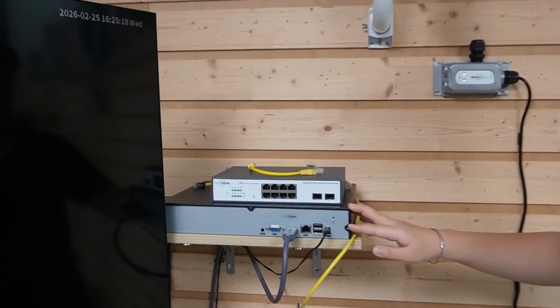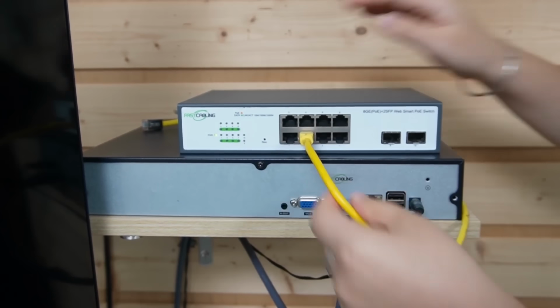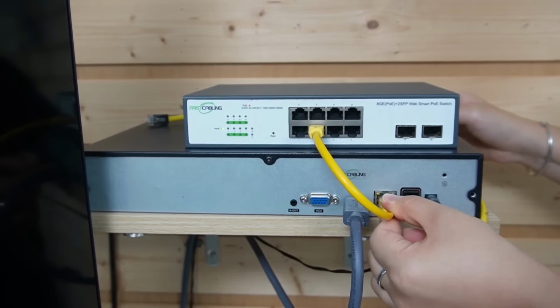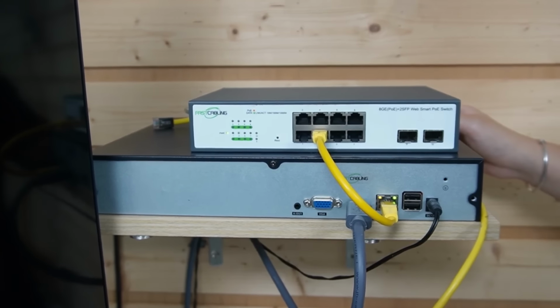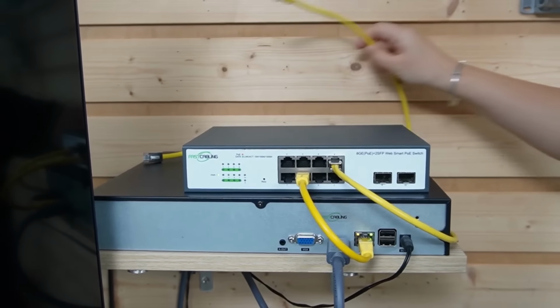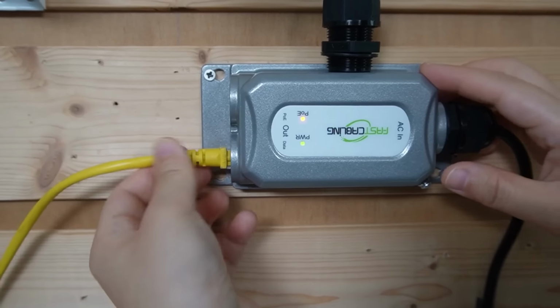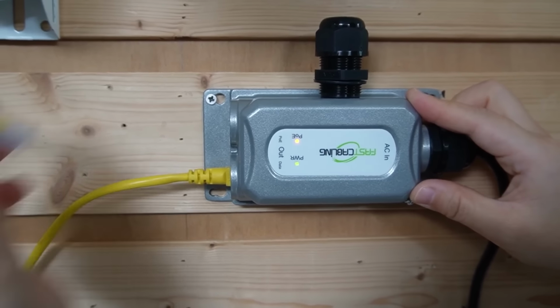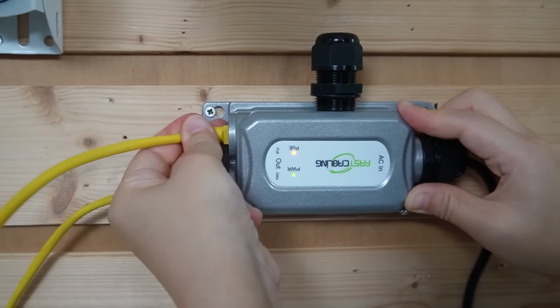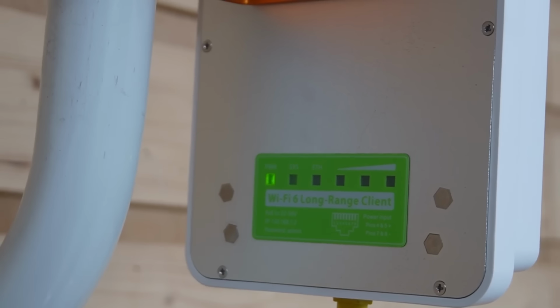So here's the full setup from the bottom of the mountain to the top. At the base, we have our network video recorder and a WebSmart PoE switch. We're using a short patch cord to link them together so our NVR can display video through a big screen monitor. Using another Ethernet cable, connect our WebSmart PoE switch directly to our passive PoE injector. Let's connect it to the data port for the data. Using another Ethernet cable, connect the PoE port so we can send both power and data to our wireless bridge.